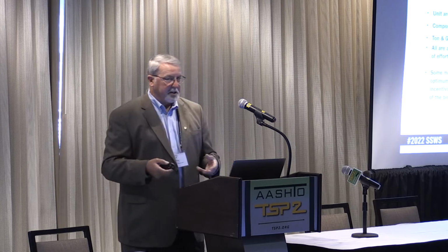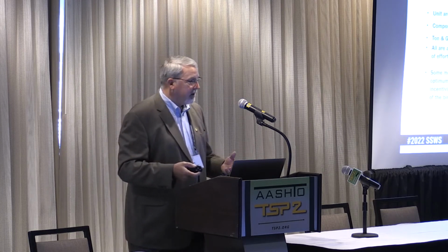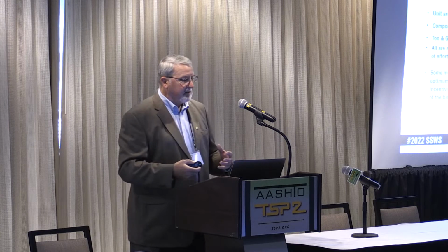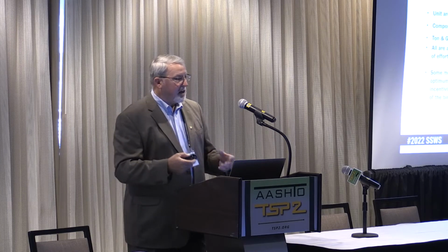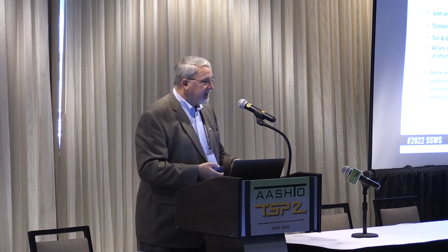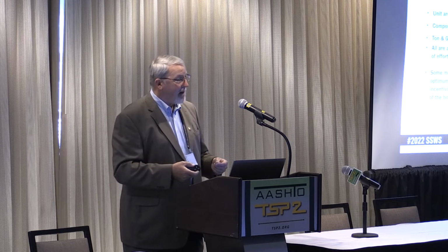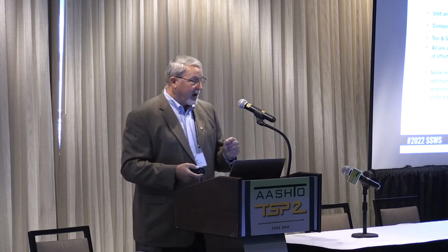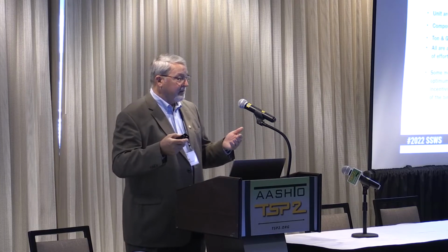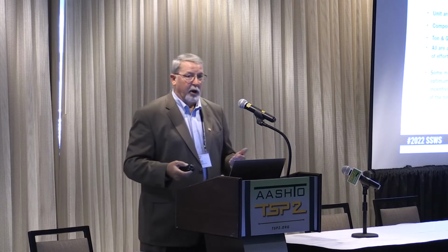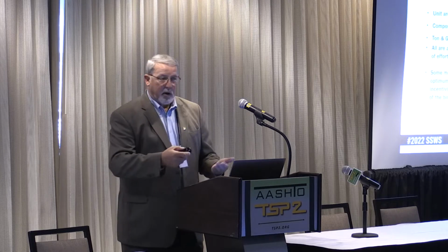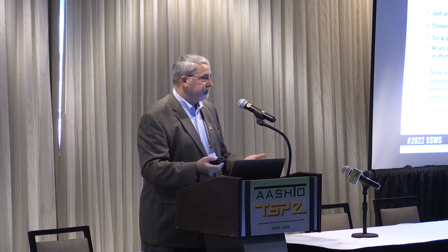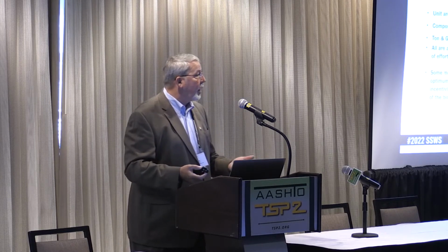So if you've got 5 and 6 contractors bidding on a project, very tight, very competitive, it kind of incentivizes that low bidder to say, I can run 0.5% lower on my binder or my emulsion content because my number's really not that good on this job. We got it, but I'm going to try to increase my profit. And that will incentivize him to run on the lower end of that design rather than at the optimum level. That's not really a good way to approach it.